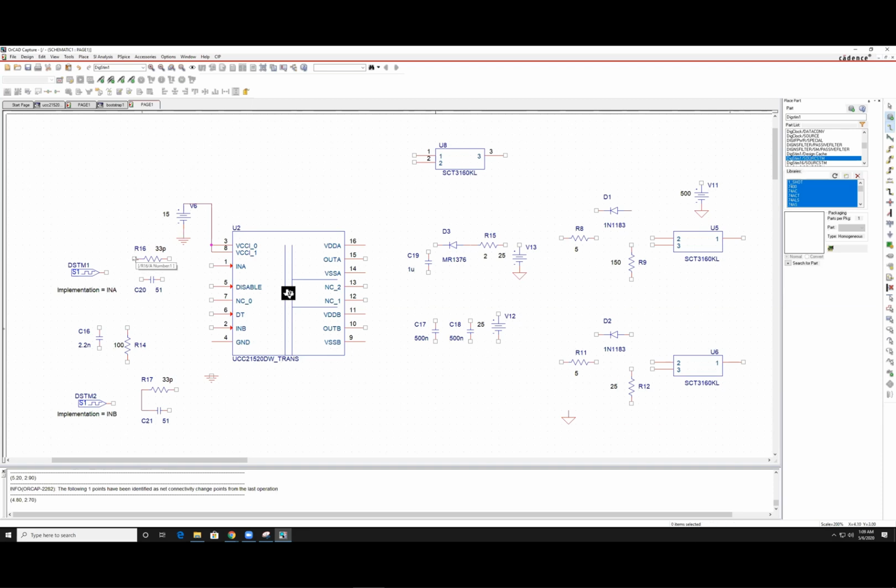And we want to put these in parallel, again in parallel. We put this one connected to the high voltage PWM input, and this one to the low drive. You will actually ground pin 5 and 7. Make sure you don't connect those. It actually gives you a red warning sign that it's going to connect. Very helpful.